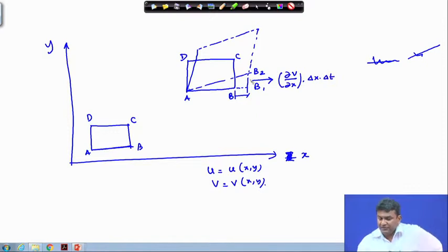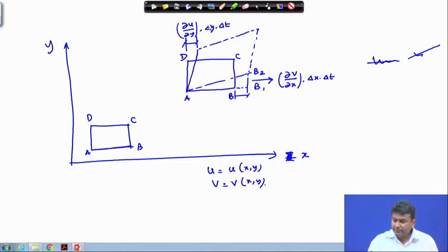So, this section arises because the y component velocity of all points in the y direction of the line AB is not the same. Now, you also have an angular deformation here. This one we can calculate as del u del y into delta t.